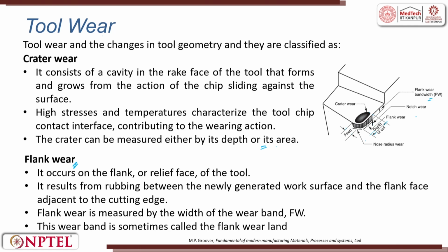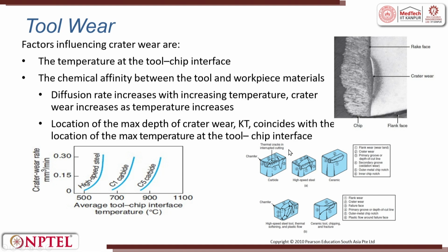So, we say flank wear, and if there is a sharp dip, it is called notch wear. This is the nose radius. Now you can see that on the rake face comes the crater, and on the cutting edge relief comes the flank wear. The factor influencing crater wear can be temperature.